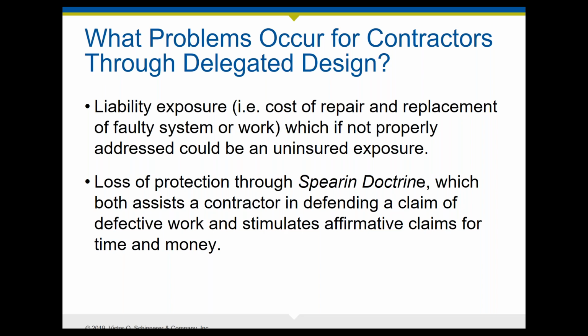Now, I have to say that we talked about some states, and states vary. Design delegation sometimes is prohibited unless those services are specifically required by the contract documents, or the contractor must really do the design to fulfill the responsibility for its own construction means and methods. And again, the states are very careful about if the contractor has to produce a design solution, the design professional in charge must specify all the performance or design criteria that must be satisfied, and has some level of review and approval of the contractor submittal for conformance with at least the design concept for the project.